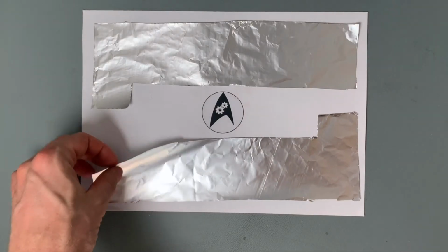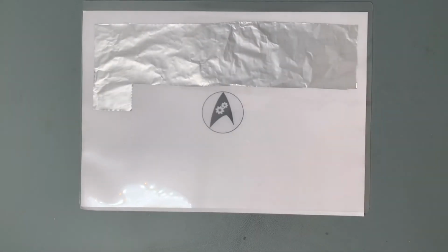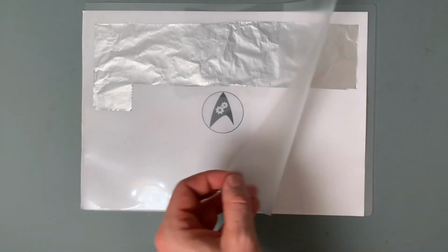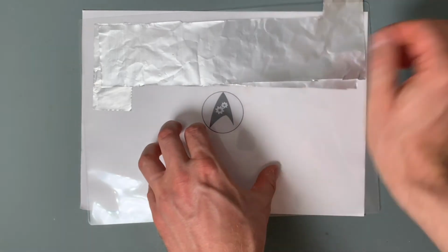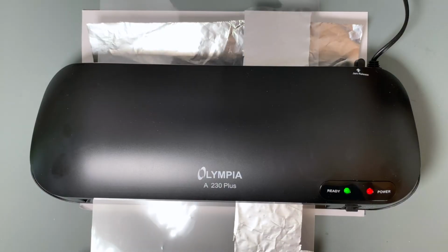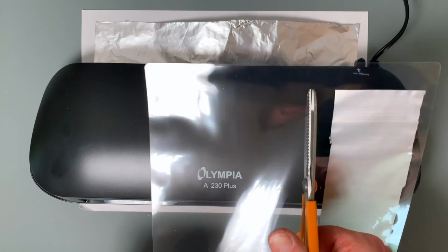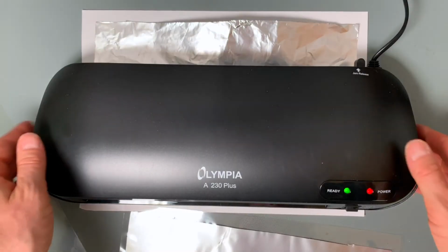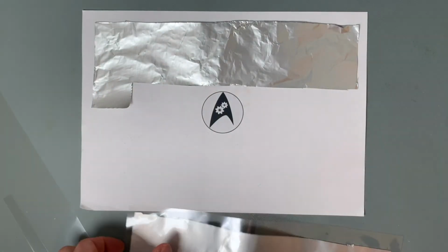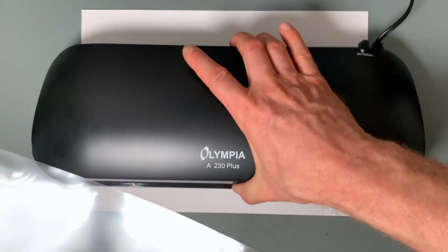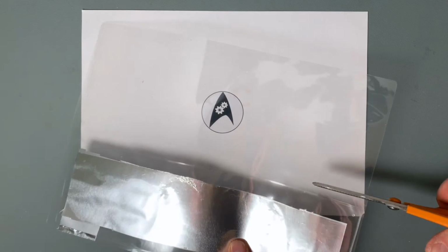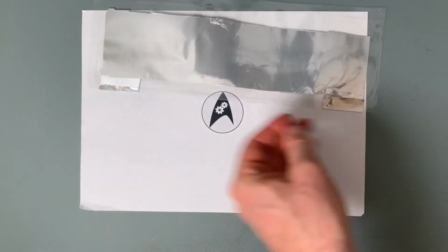So let's quickly build a capacitor of our own and measure its capacitance. To do this, we only need 2 pieces of aluminum foil and 2 laminating pouches. Let's first laminate the first piece of aluminum foil and run it through the machine, making sure that a piece of it sticks out of the pouch so we can use it as a contact later in the circuit. Once we're done, we place the second piece of aluminum on top and put both pieces into a second pouch and laminate this pouch once again. And now we have our own do-it-yourself capacitor.